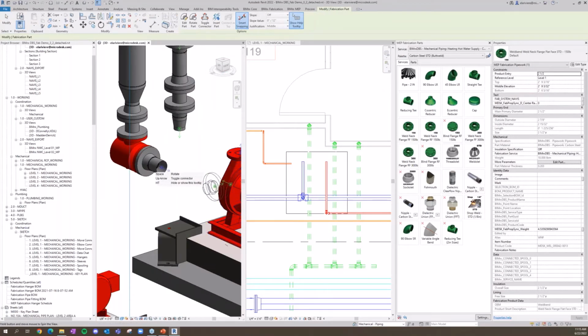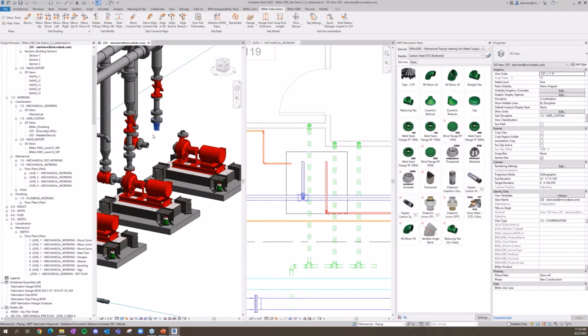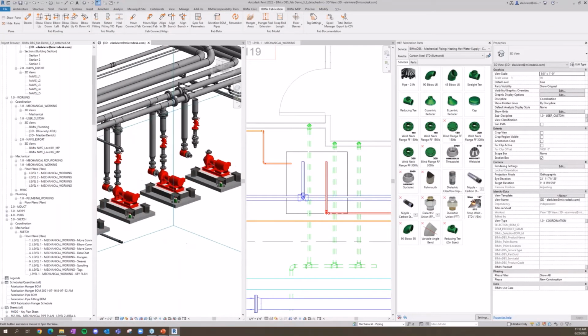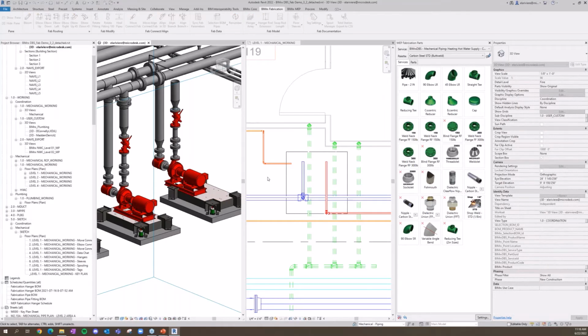You just move it nice and over, make sure you can see it, and a quick up arrow gets those things connected, right? So having those flanges in here, I can then use move connect to bring the rest of these elements together and make sure they're connected. So the move connect command is allowing me to choose 2 elements and it move connects them. Choose 2 elements, move connects them.